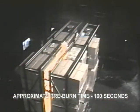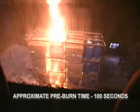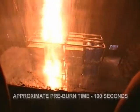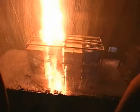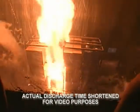The flammable materials were ignited and allowed to pre-burn for approximately 100 seconds before the system was actuated. This is well beyond the normal reaction time a typical UVIR fire detection system would normally take to detect the fire and actuate the foam system. A few seconds after the system actuated, the foam generators began to discharge high-expansion foam.